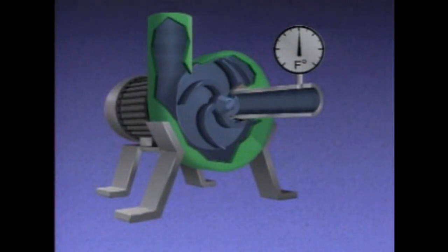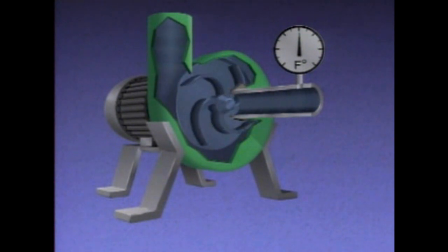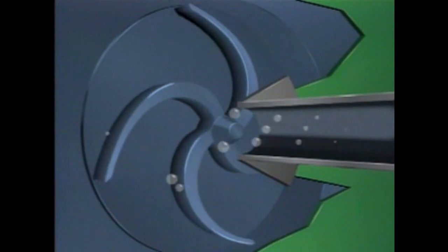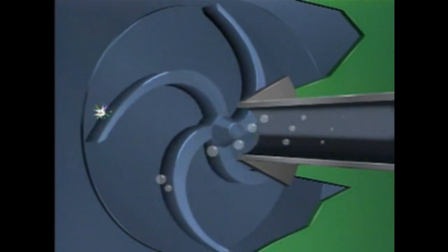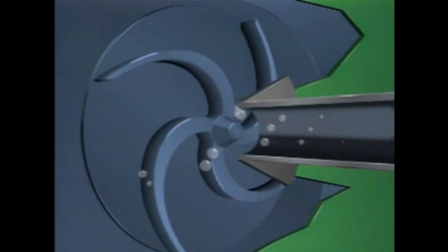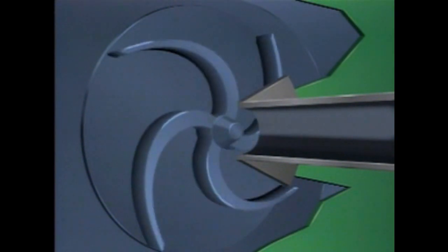In some cases, cavitation can occur because the temperature of the process fluid is too high. This causes the fluid to boil when it experiences the drop in pressure as it enters the pump. In this case, the temperature must be lowered to eliminate the cavitation.